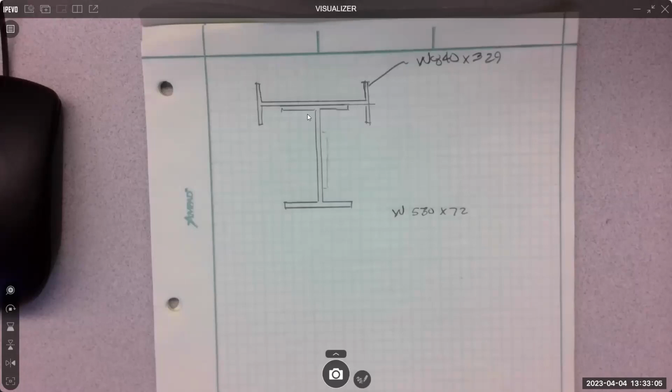That's also why your telephone poles are like this. That's exaggerated, I know, but they have wider bases than they do tops. I mean, that's why we like trees and we use them for so long. They actually have wider bottoms than the top, right? So they have this natural taper to them. That's because all the bending stresses are down there near the base. So we want more material here. And there's hardly any bending stresses at the top because the top's not bending, right? It's just moving around. So same kind of thing.